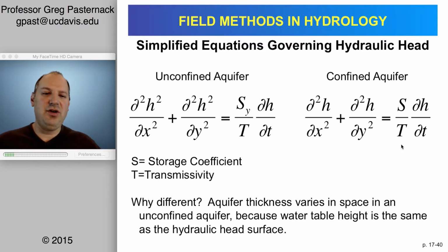And of course, you have to have some sort of boundary condition. So at the boundary, what is the hydraulic head? And again, are there any inflows or outflows? So this is a groundwater model that helps you to see the hydraulic head distribution and therefore helps you get a groundwater flux. In order to use this model, the parameters that you need to calibrate are storativity and transmissivity.